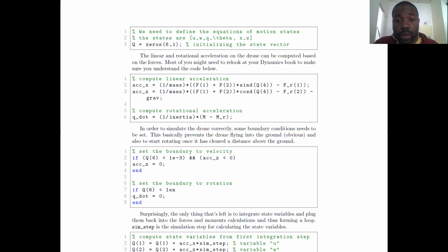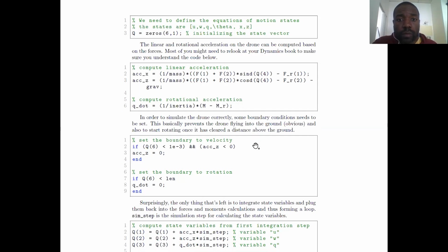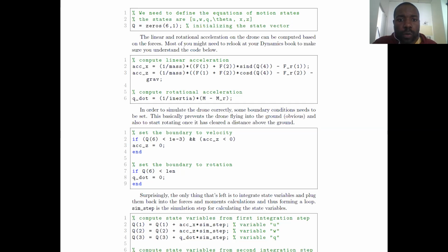But in any case, it's quite important for us to delve into the specifics. So what I was saying is that if you rotate the drone, the force vector is fixed to that body. So in terms of the up and down direction, it changes its magnitude, and that is the cause of that angle of rotation. So as you tilt the drone, obviously to go forward, you change its force or acceleration in various directions. That's what that is.